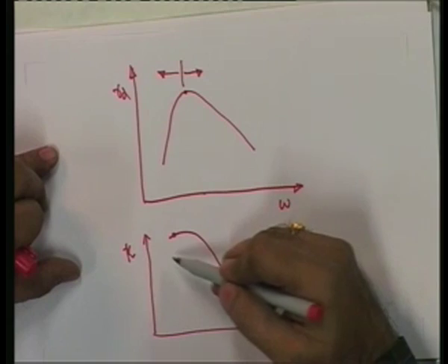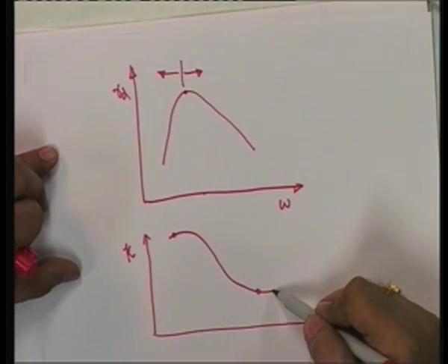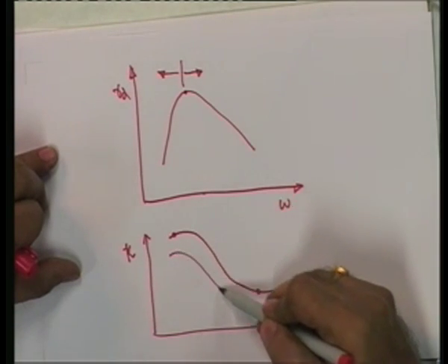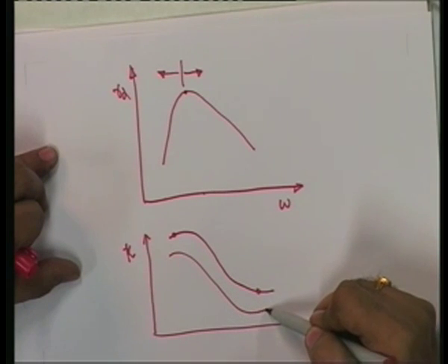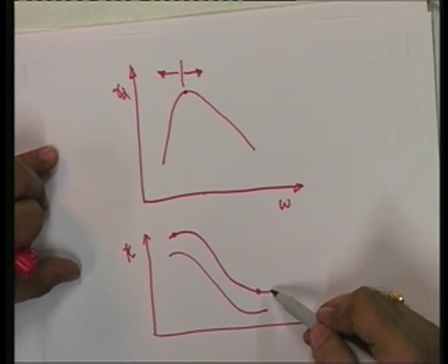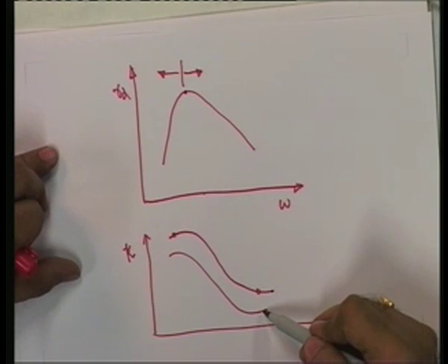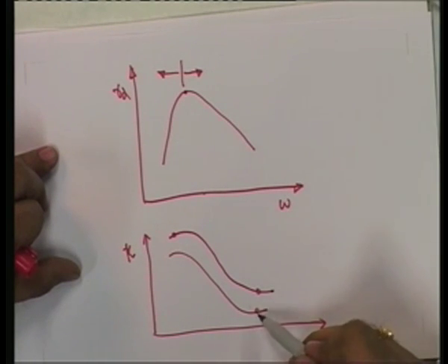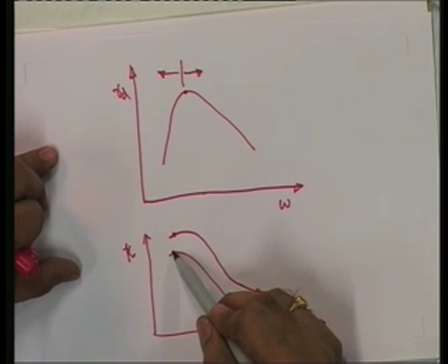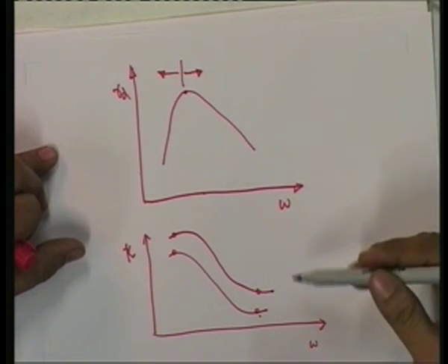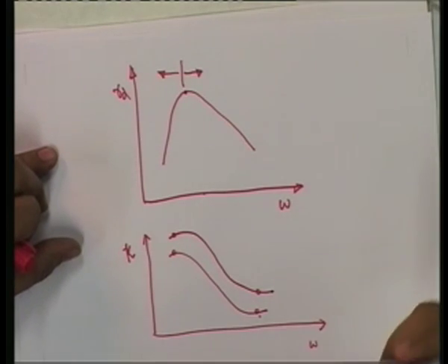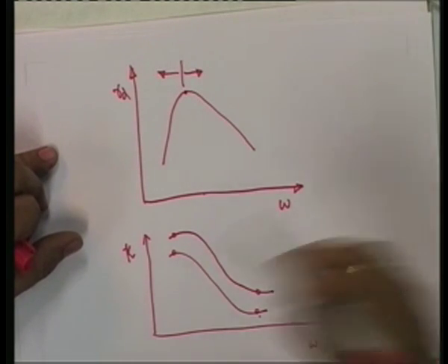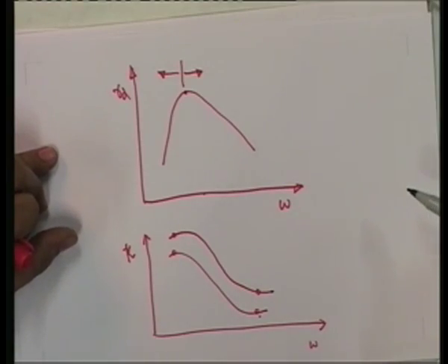Similarly, if I take this for a modified compaction, this is for a standard Proctor compaction. With modified compaction it can have a value slightly less compared to the standard Proctor compaction. So, the increase in compactive effort decreases the coefficient of permeability. Here again we connect back to the type of the soil structure which is prevailing in that moist compacted state for a given soil.